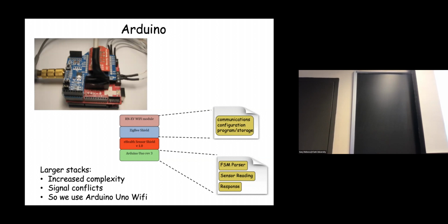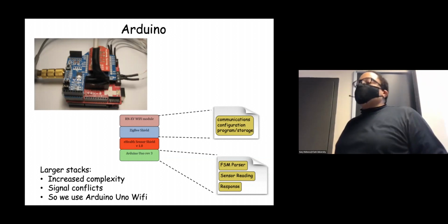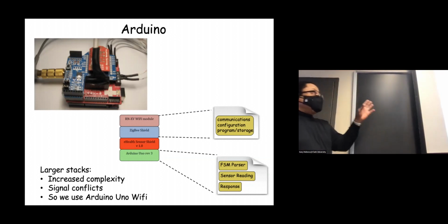And that's particularly important for applications where you're doing monitoring over a large area where you might not have Wi-Fi reach. We also have shields that implement things that you could do in software on the Arduino board. And the reason for that is because when you implement something in silicon, in hardware, you can make it run very, very fast through a simple API call. And we gave some examples of that.